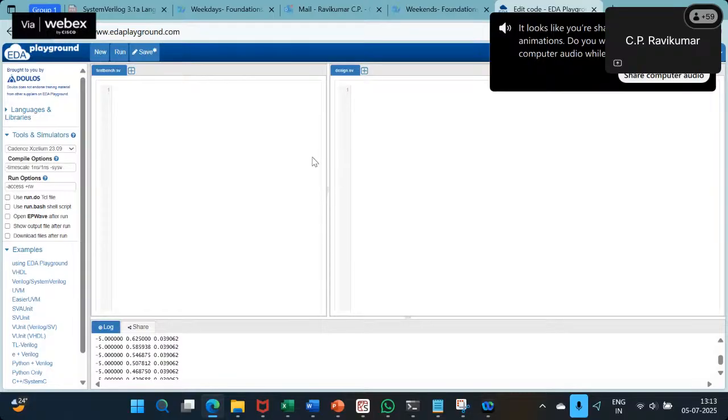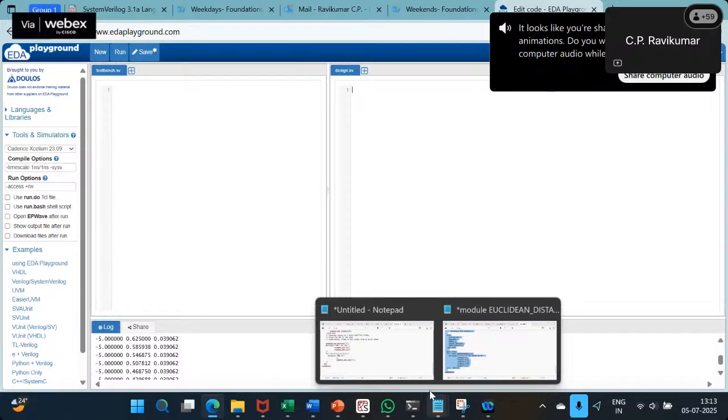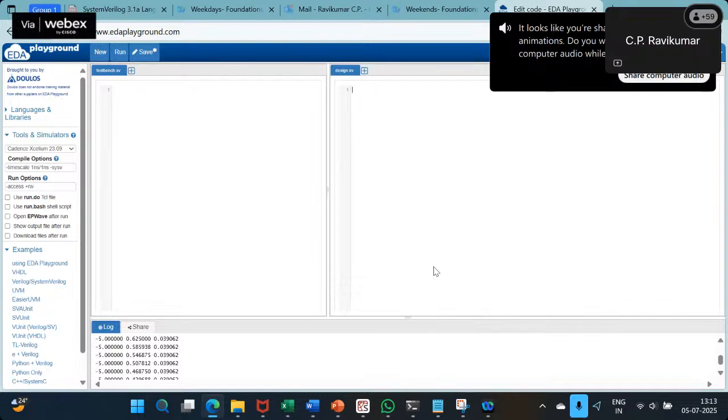The other thing I wanted to do is make that binary search. Okay, I forgot to tell you. So the exercise I am assigning to you is: modify the ADC to do binary search. Even in binary search, there are some interesting ways to do it. I think there is a Fibonacci search and many other things. So any simple binary search is also okay.